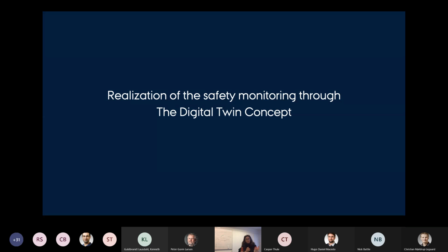And here again, the RabbitMQ is an enabling FMU that allows us to now remove our Gazebo simulation and plug in our actual robot. And immediately we can have this flow of data coming from the robot inside the INTO-CPS application, and we can have our monitors tracking different aspects of the behavior of the robot and sending feedback, intervening when this is necessary.